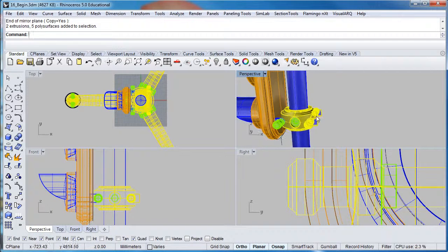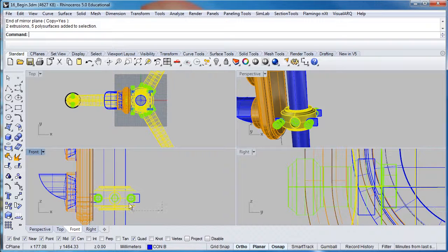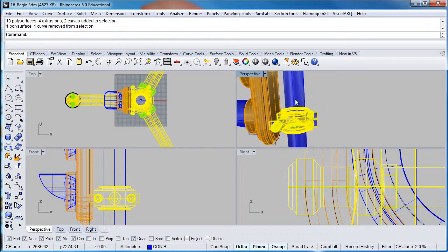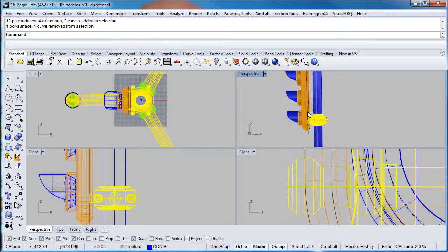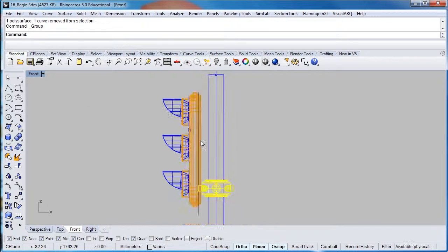That appears to be correct, so we can now select all of that bottom section. So we're just going to scroll from left to right. There we go. Then deselect. So I'm pressing down Control to take away the central pillars. So we've now just got the mounting lug and everything in position. I'm going to group that by pressing that Venn diagram. Now we want to mirror that to the top edge of the traffic light module.